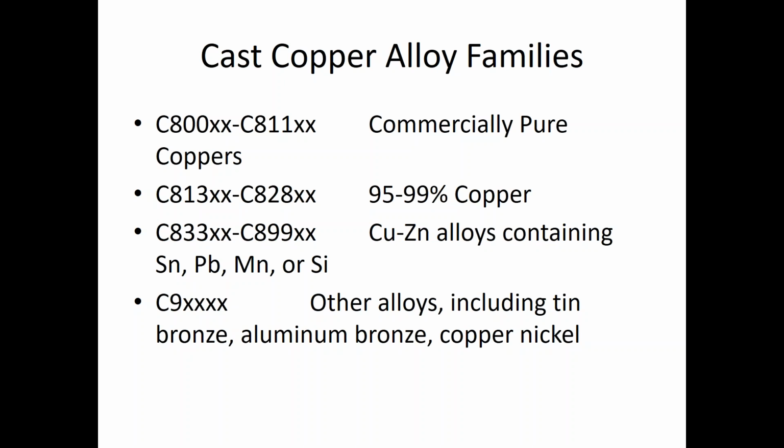Commercially pure copper are at the very low end. You have high coppers and copper zincs, or you can have them containing other things through the 800s, and other alloys in the 900s, the bronzes, aluminum bronzes, nickel aluminum bronzes, copper nickels, etc., etc.